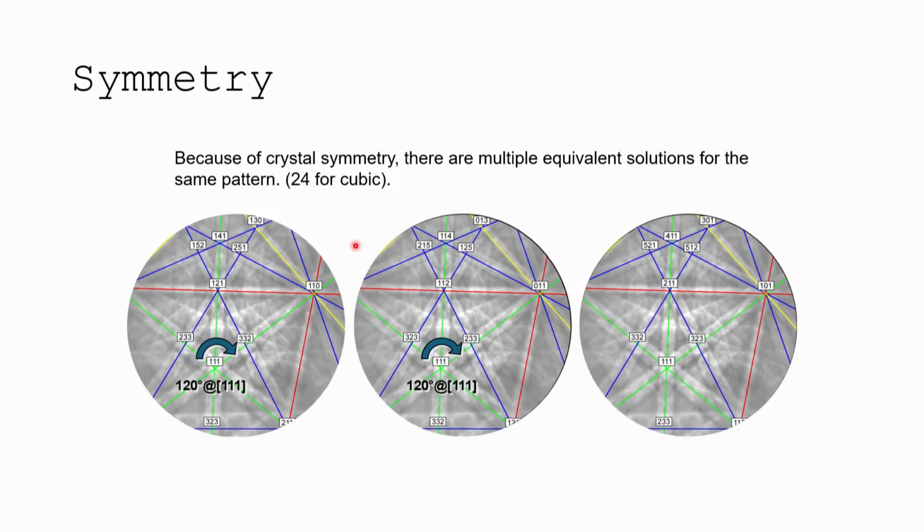Okay, we're back. Good. So there's multiple solutions then for all the same patterns. If I'm saying that we have these types of zone axes or these types of bands, let's do this one. This is a 110 band. These green ones are 110 type bands. And if the computer assigns this as a 110, then this one it has to assign as something that can have a 110 crossing that plane, right? It can't be parallel to it.